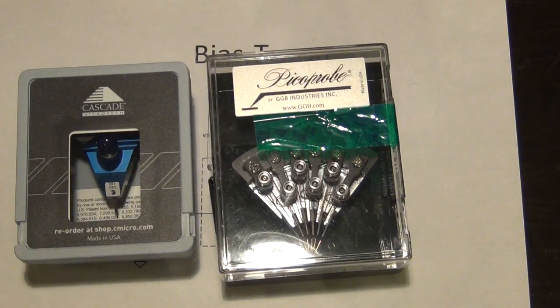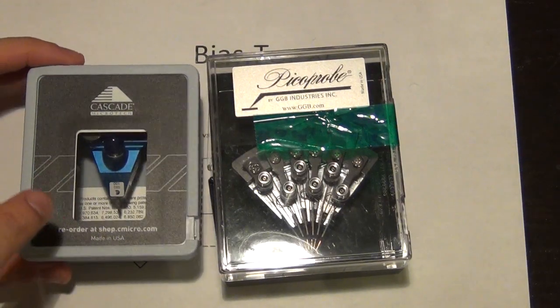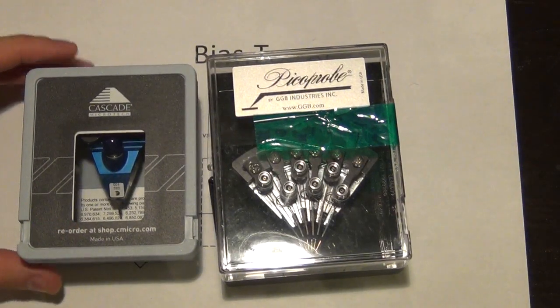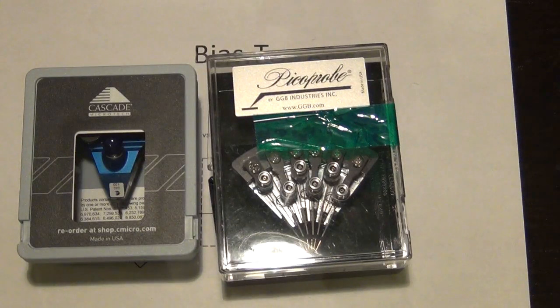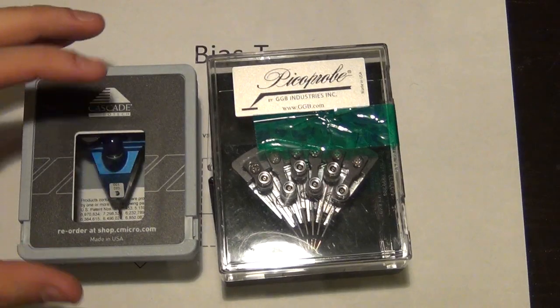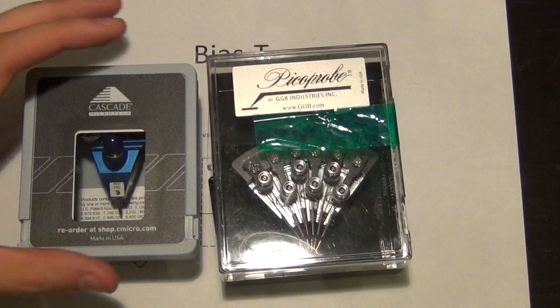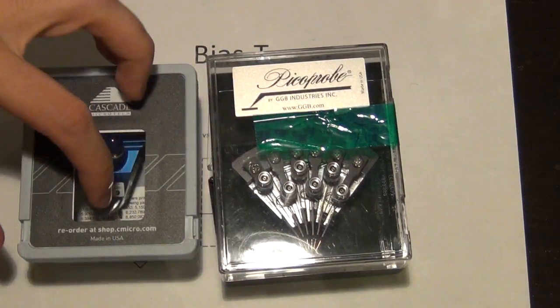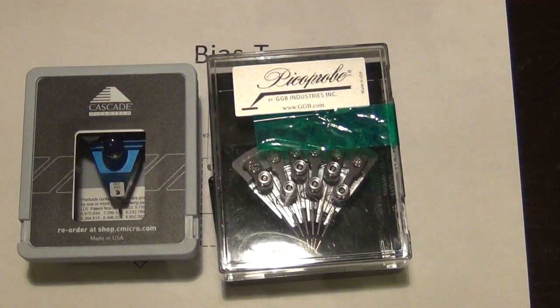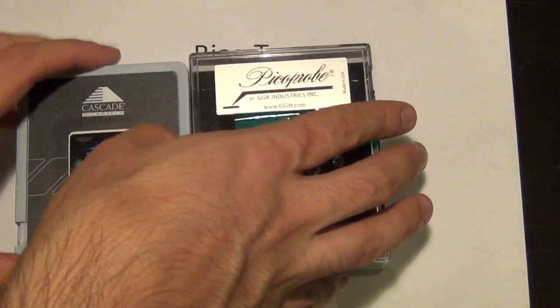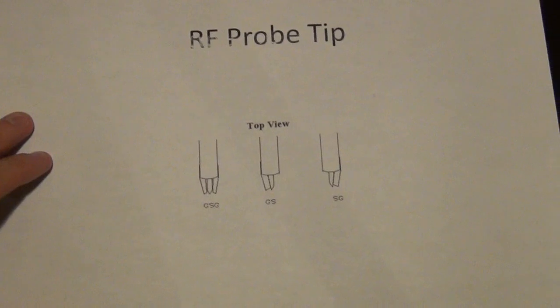So these are used in order to measure a circuit before it's placed in the package. So in a research environment, when you don't want to necessarily develop a package for your circuit before you can put it on the board and measure it, you can actually put your integrated circuit directly on the table and use this probe to come in and contact your circuit. The tip of a typical probe, for example, looks like this. Here's an example of that.